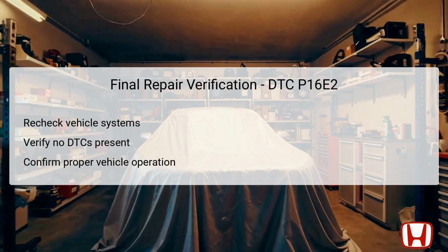After reconnecting, utilize the Auto Diagnostics System, HDS, to verify no DTCs are present in the system. Confirming the absence of DTCs is essential as it indicates that all previous issues have been resolved effectively. Lastly, conduct a test drive or simulation, if applicable, to confirm the vehicle operates smoothly, ensuring that the electrical systems function without interruption or malfunction. Ultimately, this step is crucial for ensuring that the repair made is both effective and reliable.